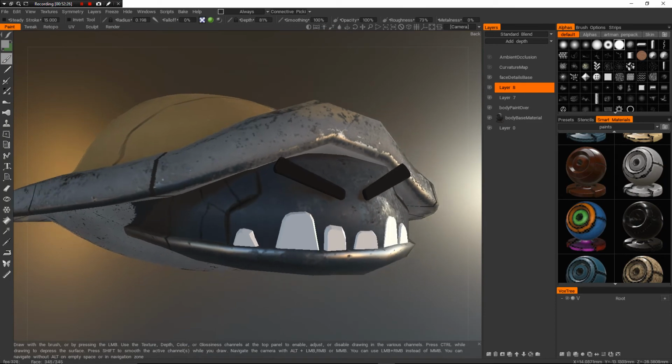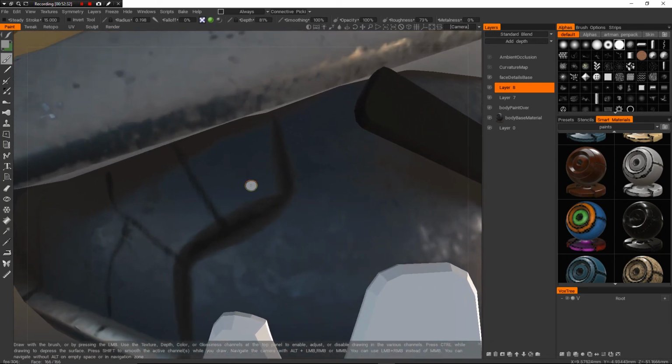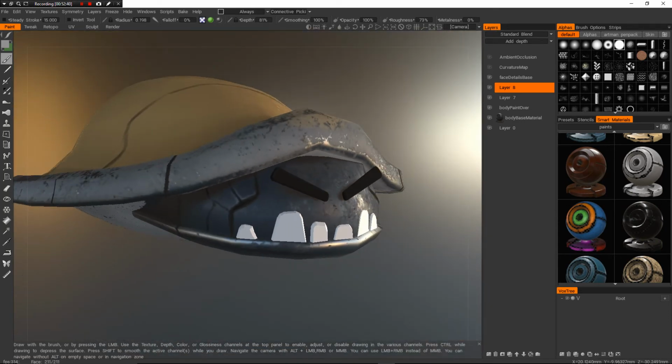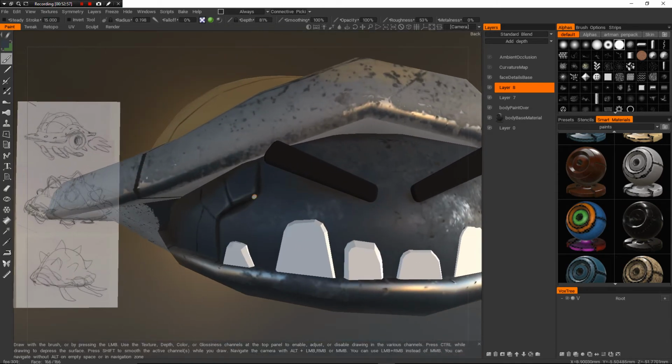If I wanted to just pinpoint a certain area, I can press Shift Z, and it'll basically make that my pivot point. So I can kind of get in there and really detail it the way I want. Too heavy, so let me change my brush type here to this. Select here. Just kind of dial that back a little bit. I can go in here, select a darker color, paint little splotches or patches to kind of get little dents and dings.